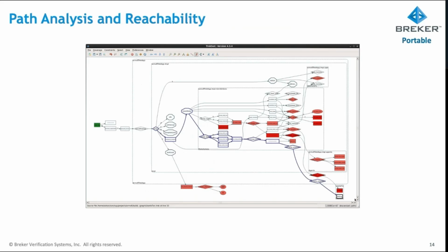So this basically provides essentially a large state machine, if you like, or a large series of tests, not unlike what you would expect in a formal verification tool, which decomposes the design into its state space in time. This is decomposed in the model, and we can do things like perform reachability on this. So what we're able to do is check all the paths in that design in a hierarchical fashion, work through the diagram and see if there's any parts of this which are unreachable.